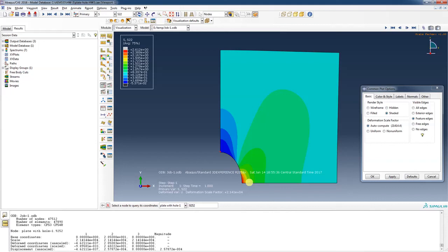It could be a crack, could be a hole, could be some sort of notch. Those sort of things cause steep stress gradients. Near that stress gradient, you want to locate the densest part of your mesh. And away from that, the stresses don't change very much, so you can get away with larger elements. In order to pick up the stress gradient, you need a lot of elements in that spot.